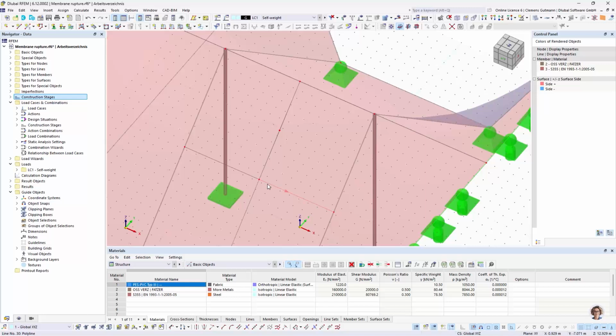So we assume that this rupture, which is a dynamic process, will stop at the weld and maybe run along the weld, but it won't cross the weld. So this is an assumption that I make here.